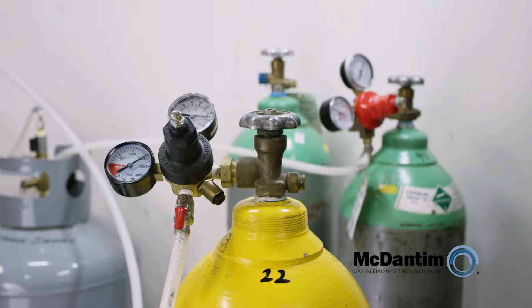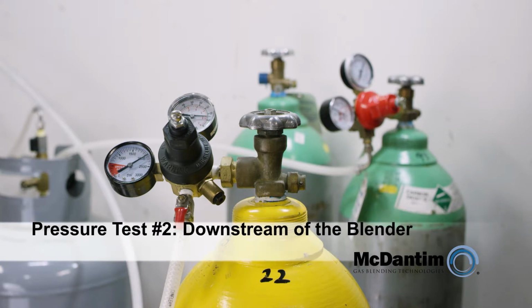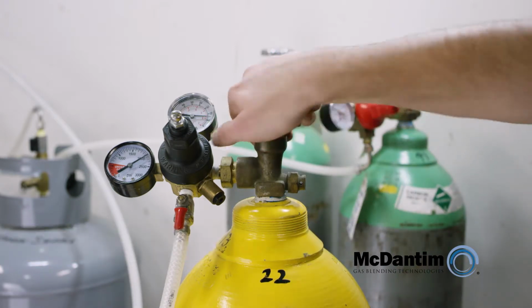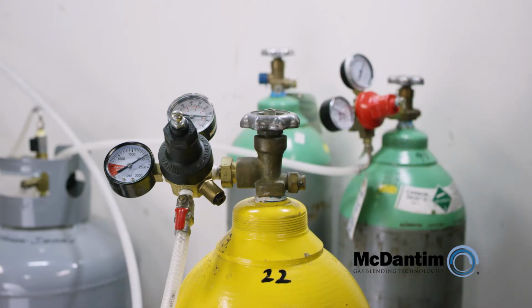If no leak is found during the first test, then it's time to move on to the second pressure test, which leak tests gas pressure downstream of the blender. Step 1. Make sure to repressurize the nitrogen system by turning on the valve on the nitrogen cylinder. Let the system pressurize for a few seconds before moving on to the next step.